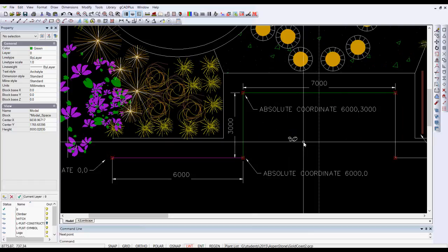So I hope that you can see by this very long-winded movie that there are a lot of different ways that you can enter coordinate position. Entities such as lines, arcs, circles and so on can all be entered in this way using the various systems. So I hope you see the value of the right mouse click while you're in the middle of drawing one of these entities and then using a pop-up coordinate system box.